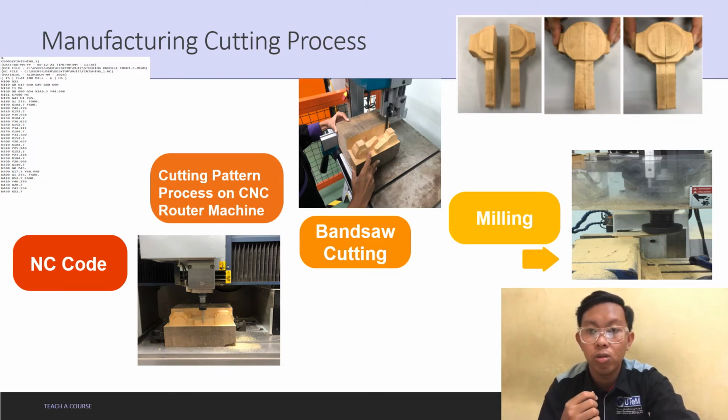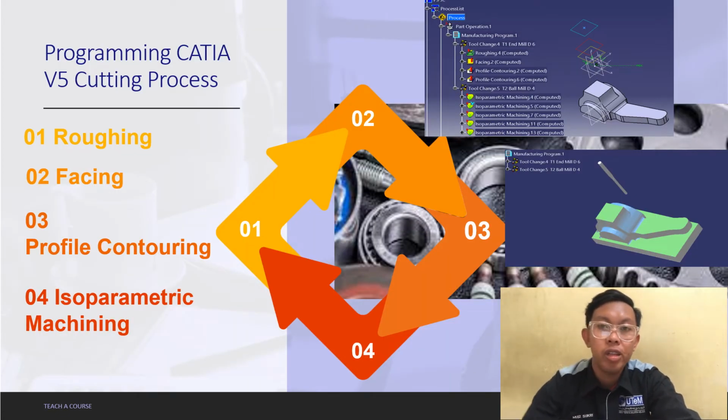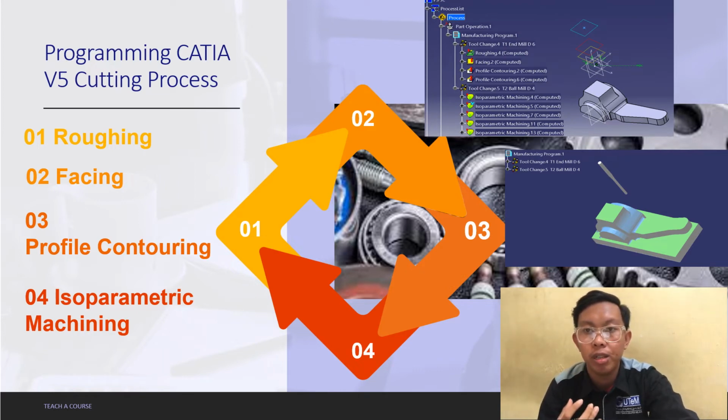The blocks are used to form the pattern making in the wooden blocks. Okay, after we created the machining program for both sides of the Steering Knuckle from C, the NC code is generated. The figure shows part of the NC code for the machining process of pattern making. Then the NC code was installed to the PC for the CNC router machining to make the pattern mold.